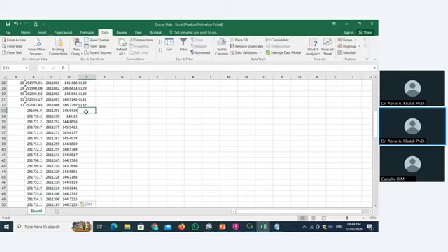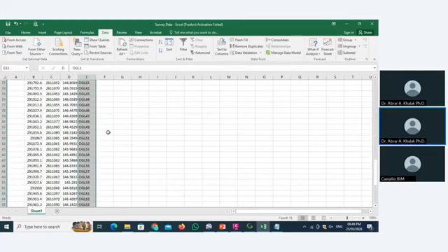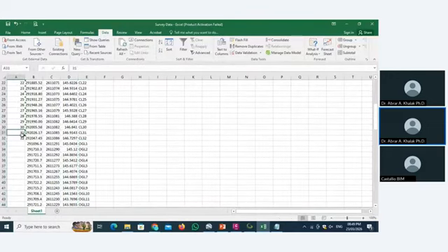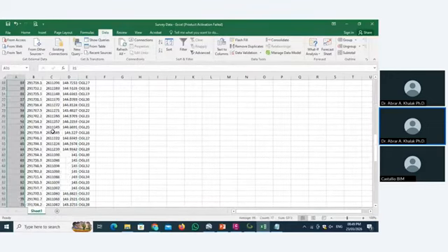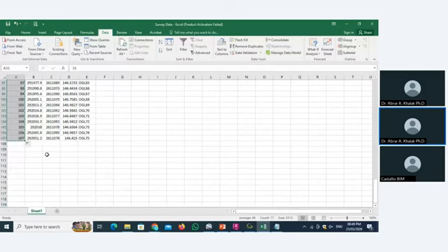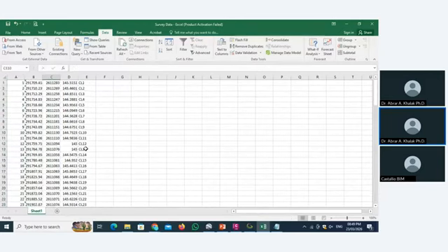Now we give a description as OGL, original ground level, point number 1, OGL point number 2. So done. So we extracted this many points here, 31, 32. Then we go again. In total we have 107 points.